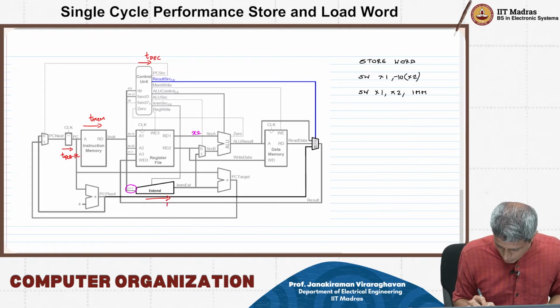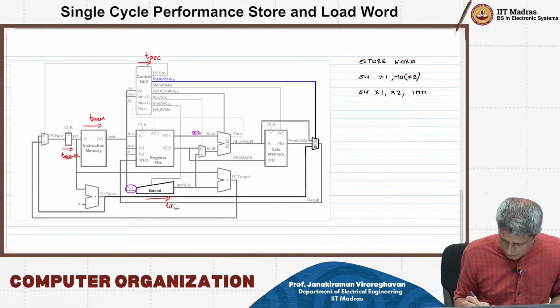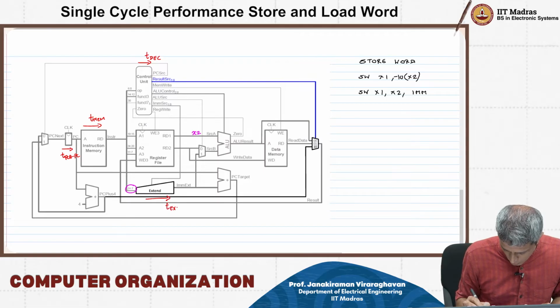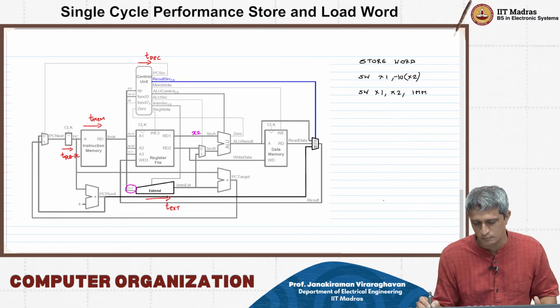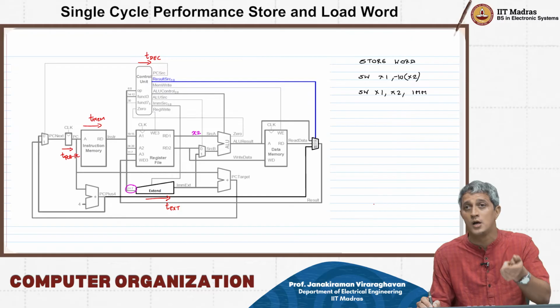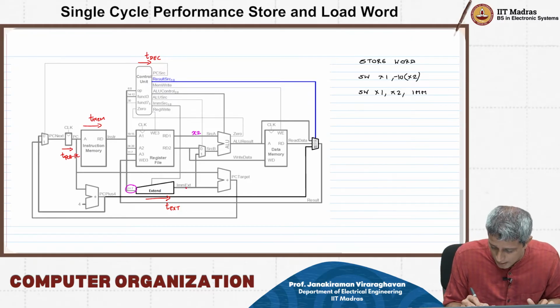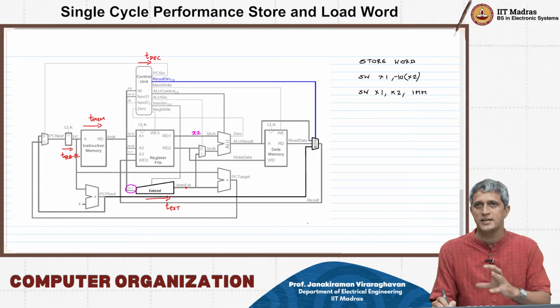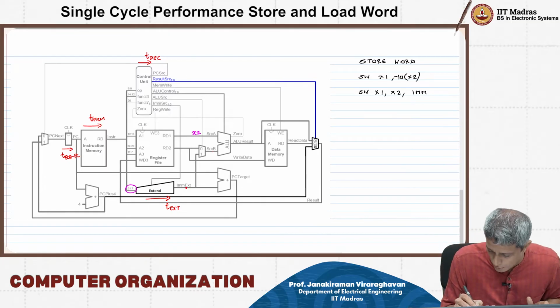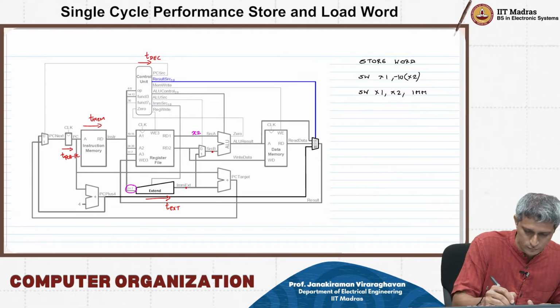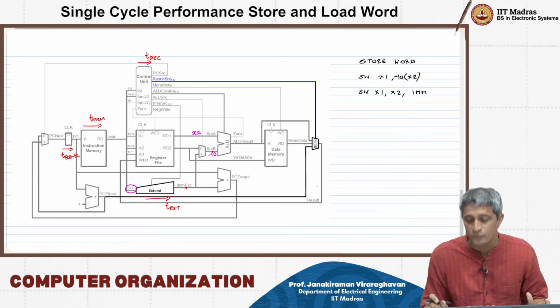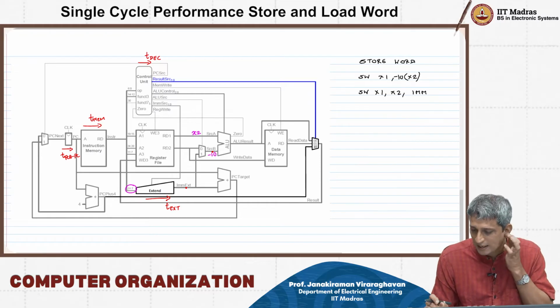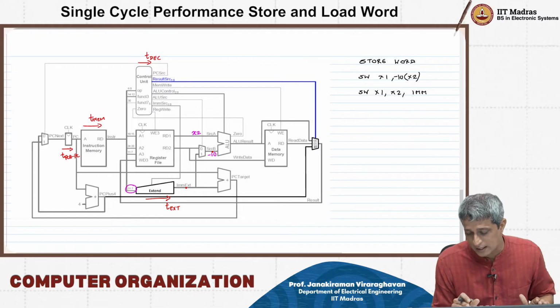So you will have a T extension, right? You're going to come through that, and then you're going to go through this. You're going to have a T decode plus T extension for data to be available at this point, right? So that minus 10 gets sign extended and then it is going to come here. So this will be some minus 10, and this ALU result has to be evaluated and it is going to go to the address.